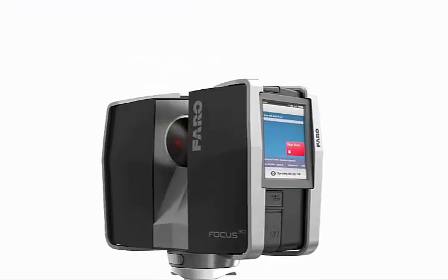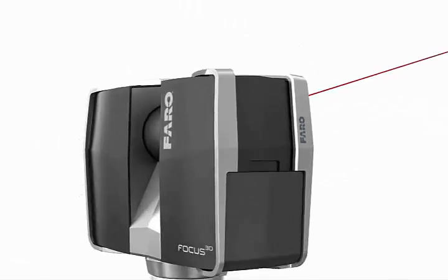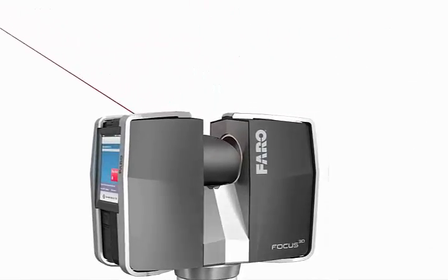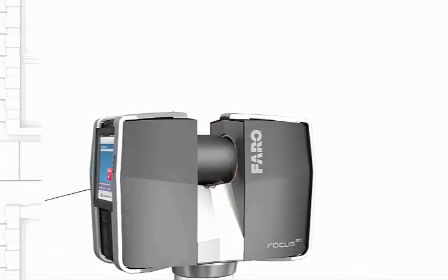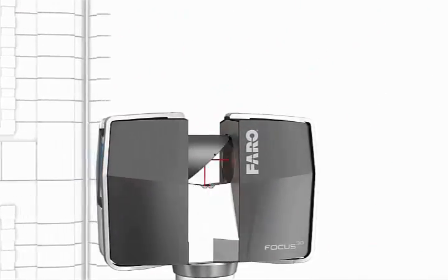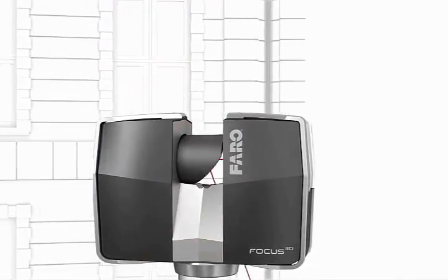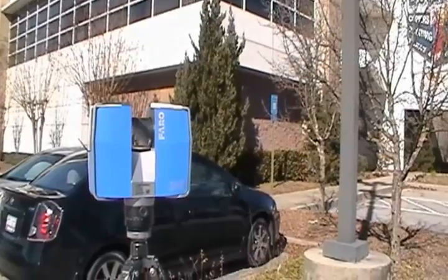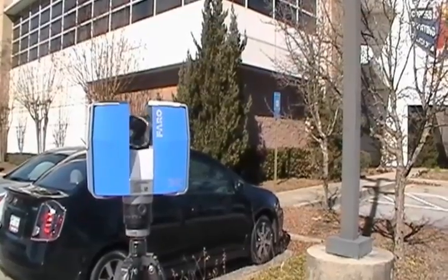To capture the scan data, the scanner uses a laser that is bounced off of a spinning mirror to measure the distance to the point the laser hits to an accuracy of 2 millimeters. As the mirror spins vertically, the scanner captures a column of data, and as the scanner rotates horizontally, it captures a complete 360-degree dome of points. The scanner can capture up to 976,000 points per second, and the final collection of points we call a point cloud.